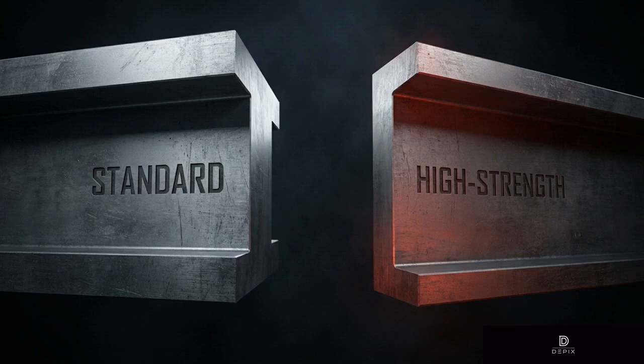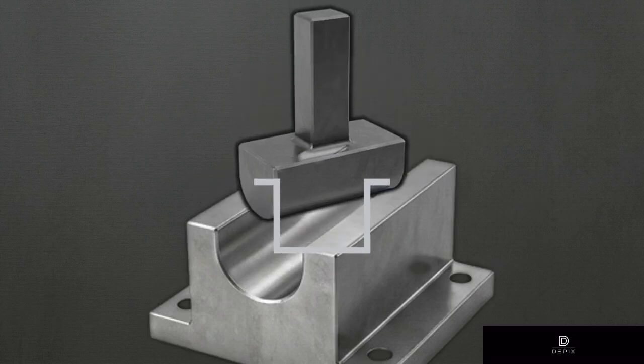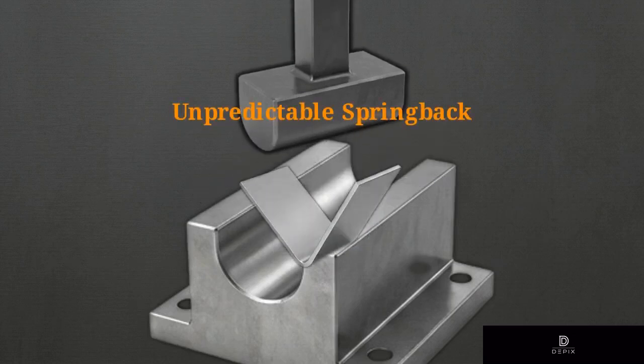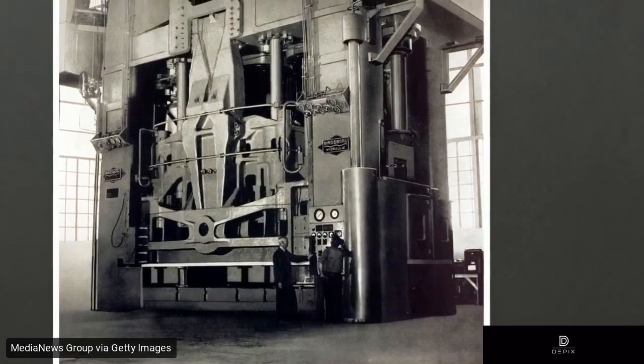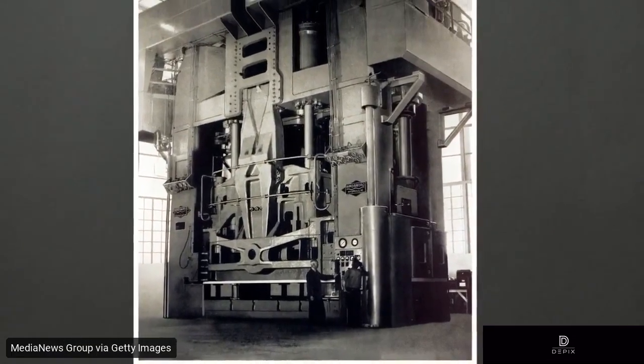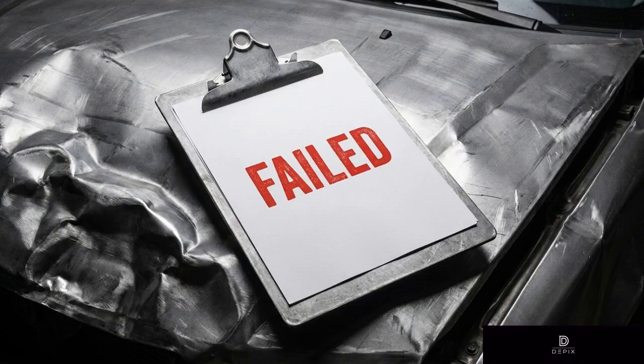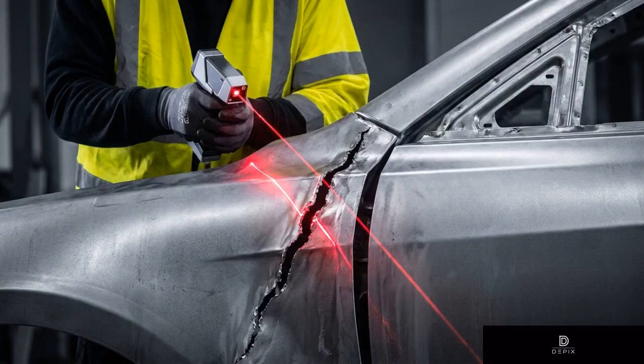Modern high-strength steels make this worse. They raise flow stress and thin the sheet simultaneously, causing unpredictable springback that varies across the part based on the material's orientation. Firms answer this with trial and error, overcrowning hoods on heavy tryout presses, hoping the physical steel matches the math. By the time you rely on a tryout press, quality verification is retrospective. You are only reading the failure off a part that is already broken.